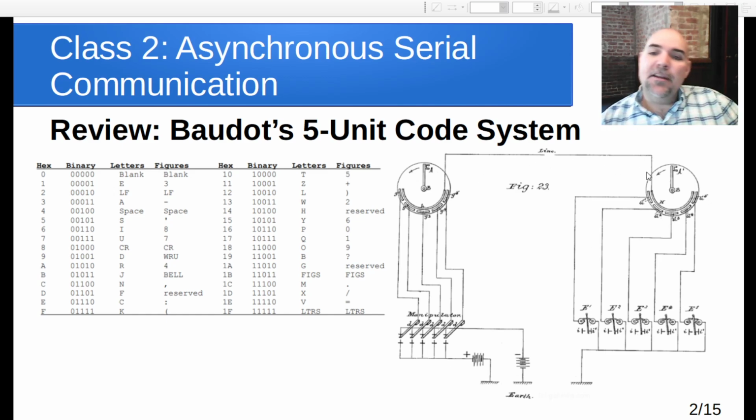On the other end, there's a rotor that's rotating in the same position at the same speed. So when this one is on the first bit, or bit 0, that one's on the first bit, and that latches that into this thing. When this completes a rotation, the pattern on the switches here would be copied onto these little latches over here. And so now we've transmitted those 5 bits, but they've gone across one single wire by using that line 1 bit at a time.